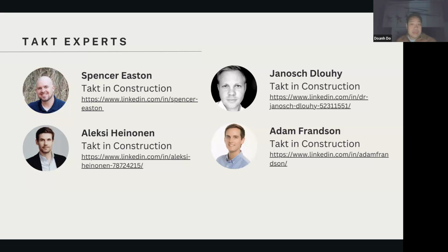Even with line of balance or location-based planning, you might actually plan in some waste. That's why we go towards teaching Last Planner and TAKT. Once people don't know about TAKT, they gravitate towards line of balance or location-based planning because it is a logical next step, but the final evolution would be TAKT. Totally agree.